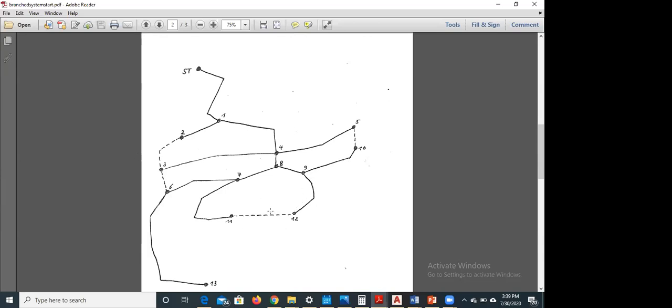The diameter of the pipe is what you don't know. But you cannot get the diameter of the pipe if you don't have the discharge. Then the elevation at each point, your surveyor has done that, he has gotten it. So we have two knowns, and we're looking for two unknowns: the discharge and the diameter. Once you get the discharge, you use your nomograph, which is the chart we have, and then you get your diameter. Then when you get your diameter, your design is finished.